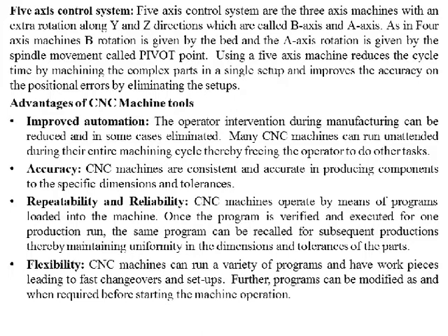It reduces the cycle time by machining complex parts in a single setup, and therefore it will produce parts with greater accuracy, and the setup times and errors will be eliminated by the use of 5-axis control systems.